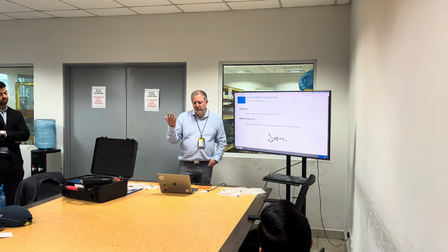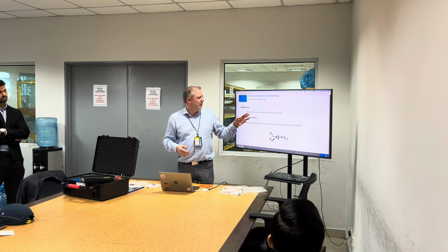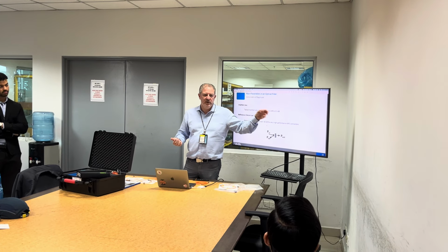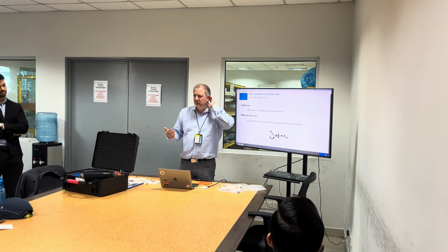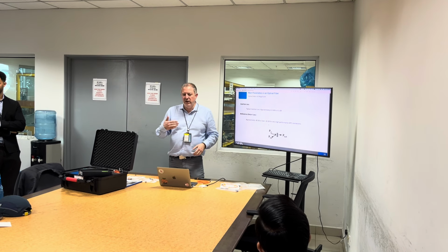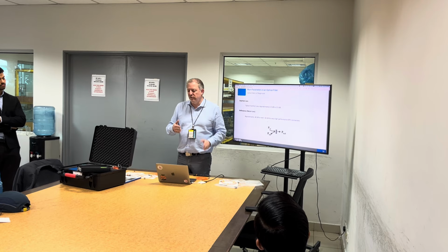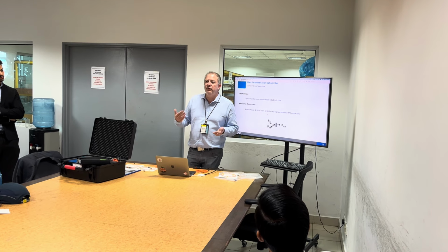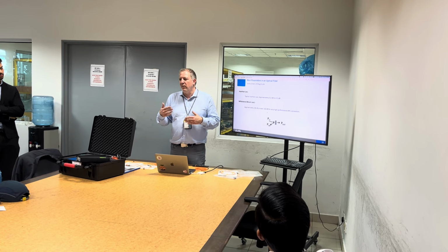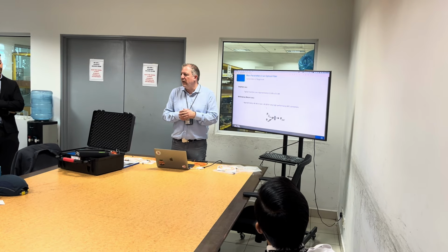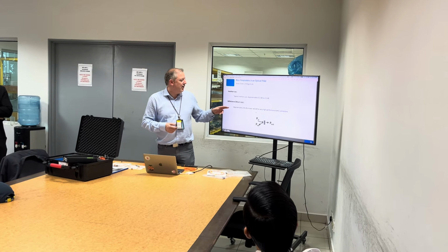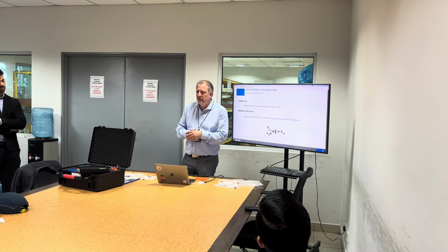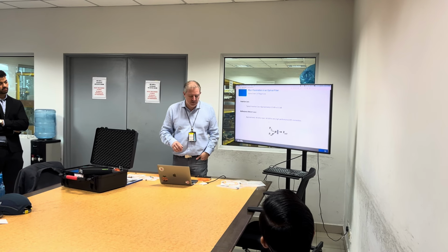Also, for you to have some ideas, a typical insertion loss at a connector point would be between 0.2 and 0.5 dB. So that's what we are going to look at. Usually, specifically in aviation, you can tolerate big insertion loss as long as you don't have insertion loss in all connectors, but 0.5 is still good. If you start to see minus 1 dB or minus 2 dB, then you may have something to fix. The return loss would range between minus 40 to minus 60 dB, but you don't have to worry much about these values.